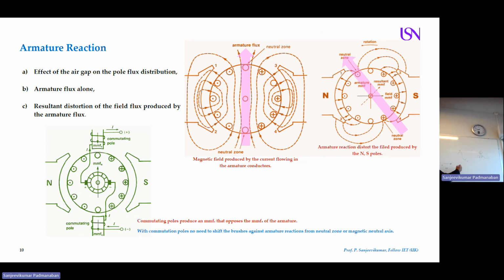I put another coil. I create a current which is opposite to this one, coming in this direction. What happened? This is plus and this is minus, so it is neutral. Clearly? So in an electrical machine, I will mount one additional coil. That is the second option. The first option, I will shift the brush, not exactly on the 90 degree, I will tilt it a little, as one option to avoid armature reaction.